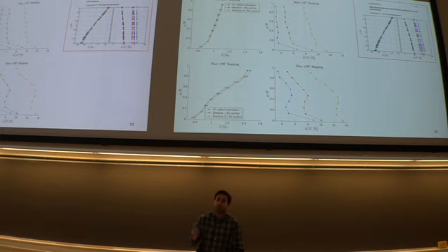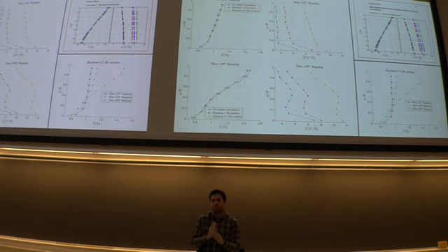And this is the results for the plus minus 90 degrees flapping, so the mode with the most shear. Here you can see, again, all of the shears are pretty close to each other. But this time the turbulence is not that homogeneous. Again, my hypothesis, which I'll consolidate later, is that this is because of production of TKE, turbulence kinetic energy. That comes from the mean velocity gradient.